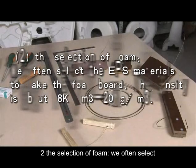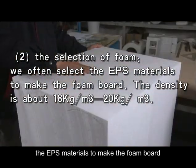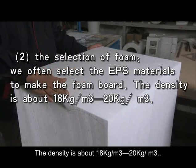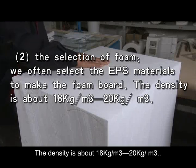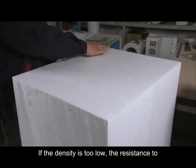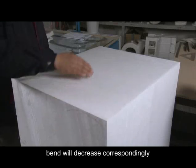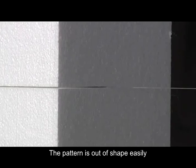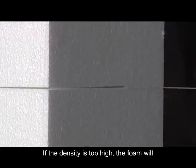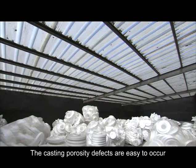2. The selection of foam. We often select the EPS materials to make the foam board. The density is about 18 kg per cubic meter to 20 kg per cubic meter. If the density is too low, the resistance to bending will decrease correspondingly. The pattern is out of shape easily. If the density is too high, the foam will increase the gas bubble amount. The casting porosity defects are easy to occur.